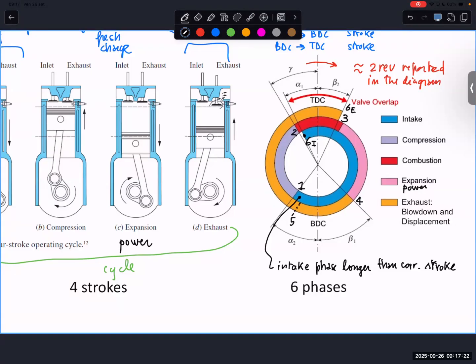we have the piston. Actually, the piston is moving from 5 to a certain point, but after, the piston is going down, so here the piston is not pushing the gases anymore, but the valve is still open, because when we are reaching the top dead center, we would like to have the valve still open. And so we have some advance or retard of closure of the valves, because we would like to have them maybe still open or not closed yet at the corresponding points.